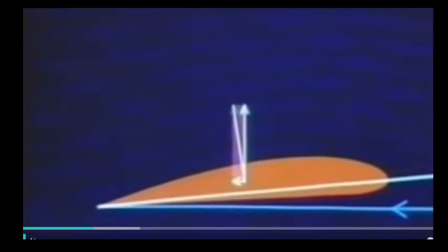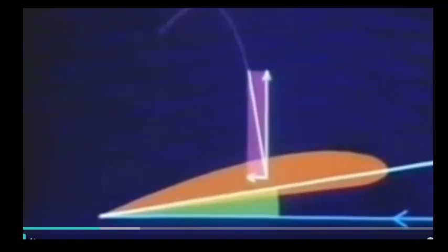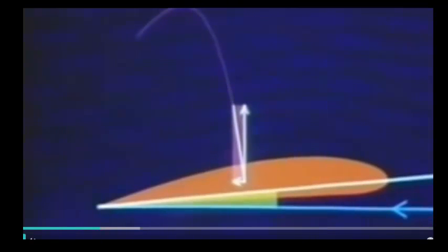If the angle of attack is increased, more lift is generated, but at the expense of increased drag. Maximum lift is produced at the point of stall. A wing is usually at its most efficient at a relatively small angle of attack. In very simple terms, a propeller or air screw is really two or more rotating aerofoils set to pull the propeller through the air, in the same way as the thread of a screw pulls it into wood.